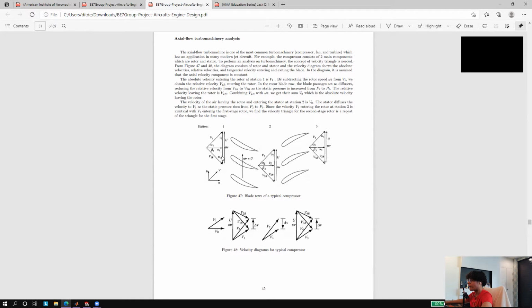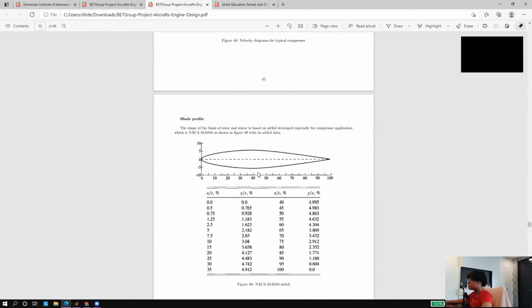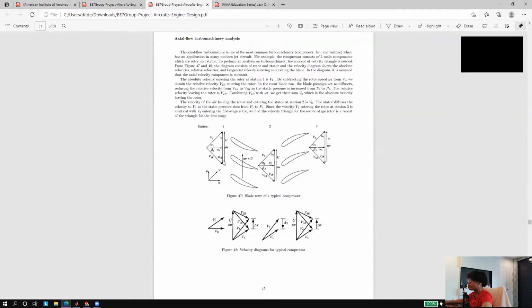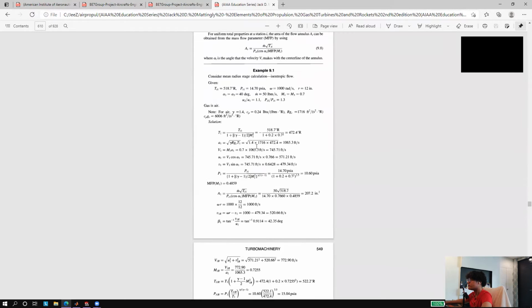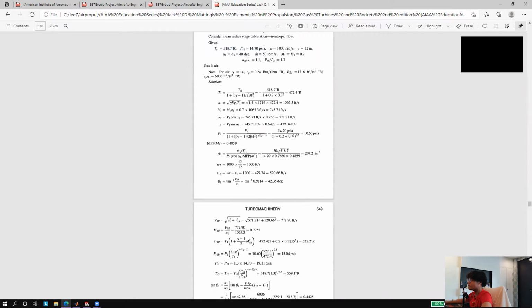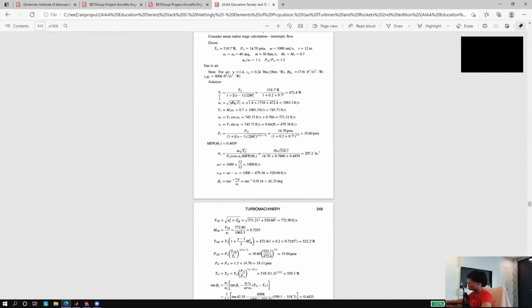The incoming flow will have certain properties, and when it reaches the blades, for example the rotor, its properties will change accordingly. As you can see from this diagram, you can use some physical relations and come up with this algorithm. This algorithm receives an input of the flow properties and the wanted flow properties. We can write this algorithm into MATLAB code, which I will show you shortly.